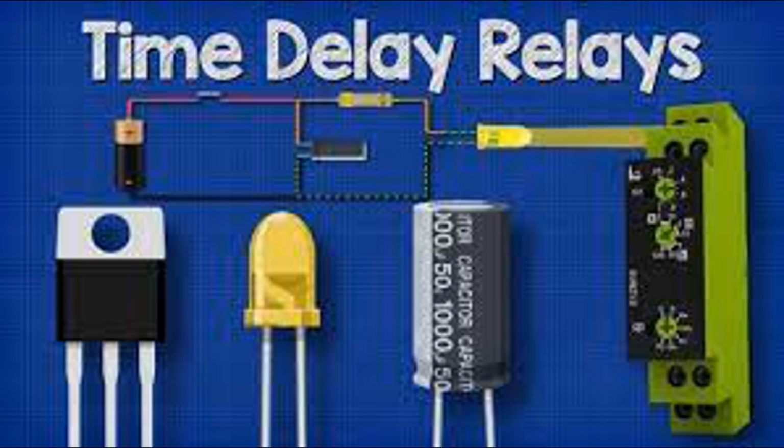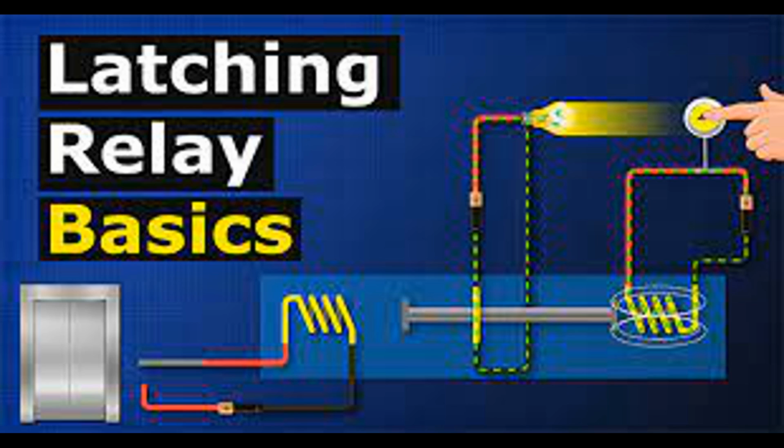Latching or non-latching operation. In some relays, the armature remains in its switched position even after the input voltage is removed, resulting in latching operation. In others, the armature returns to its original position when the input voltage is removed, resulting in non-latching operation. Energy consumption. The operation of the electromagnetic coil consumes electrical energy, which is dissipated as heat due to the resistance of the coil wire. The amount of energy required to energize the coil depends on factors such as coil resistance, voltage applied, and duration of activation.